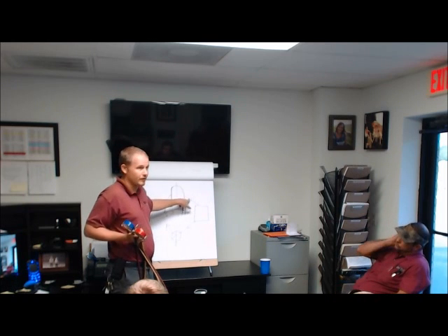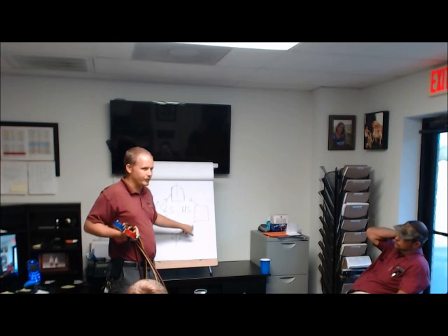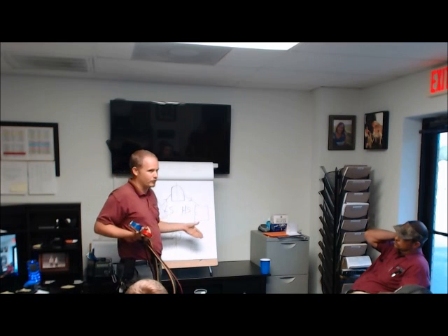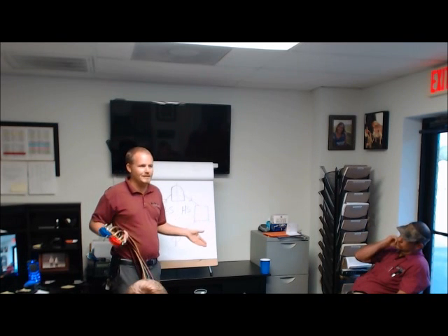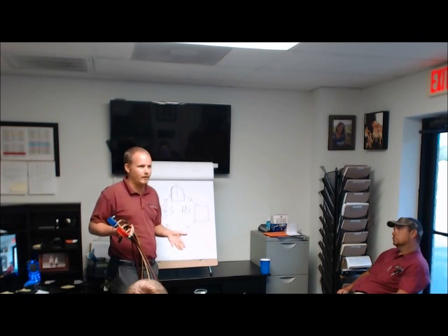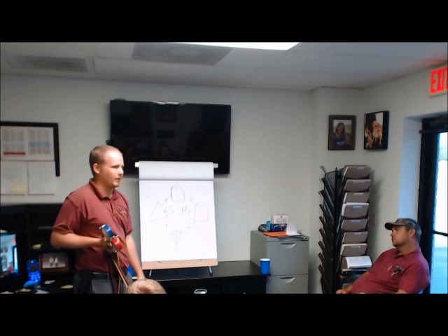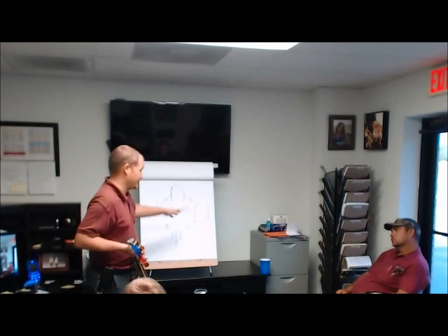So your pressure here, maybe say it's 250 psi. Well, you can't use 250 psi as your number in order to factor in your subcool at this point, because it's going to have dropped. Now, how much will it have dropped? You're going to have to kind of guess. At that point, it's not a perfect science, but you can get a good indication. Generally speaking, on a pool heater, I'll figure it probably drops 10 psi or 20 psi, and that'll give you a general idea. But it's not exact at that point.